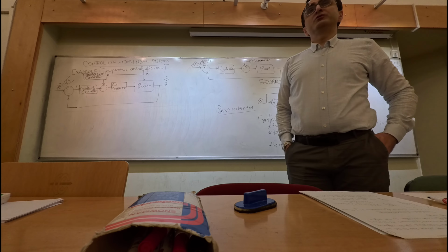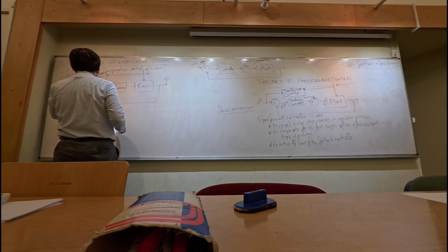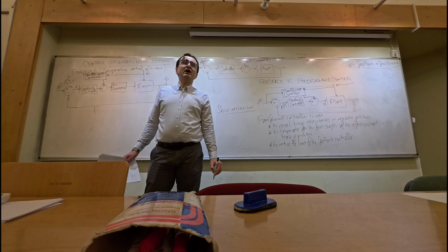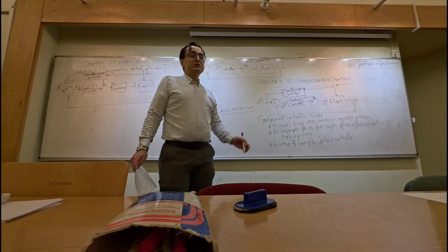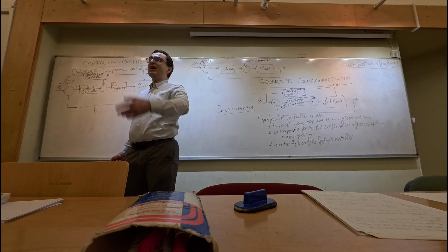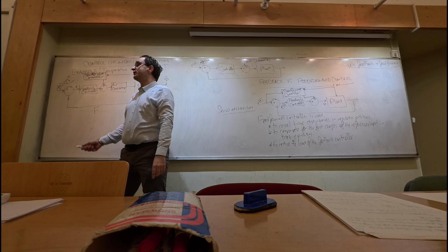So we are going to be using this type of controller idea in the control part of this course. And what we are going to do is start designing controllers by a method that is called feedback linearization. We are going to design tracking controllers, so we will actually design servo controllers. What this means is that we will want the output of the nonlinear system to follow a reference signal trajectory. And while doing that, we are going to use a feed-forward controller, which is going to take its measurements from the reference signal. So if the reference signal is changing quite fast, this feed-forward controller will start taking action before the feedback controller starts to work. So this idea is going to be useful for us in designing our controllers using so-called feedback linearization.